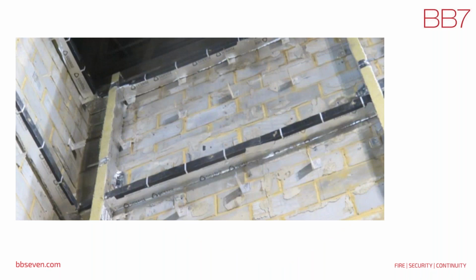Here we've got an illustration before the insulation goes on. So this has been mechanically fixed in place, and you'll notice that the vertical cavity barriers have got a mineral wool face. They are fully compressed when they fit onto the front panel, and then you've got the silver foil with the black face, which is the intumescent.